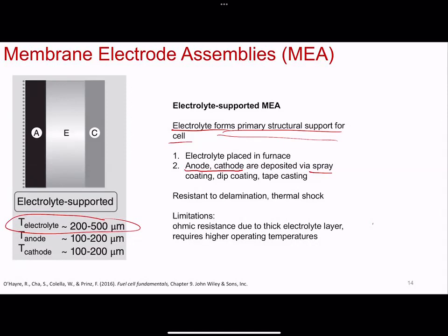Oh, wait, what was the first thing you said? Yes. So the question is, can you sputter? A potential problem, maybe it's not a problem, but something you have to consider with sputtering is that it is solventless, but you need a target. As in, you need whatever material you want to deposit. You hit your target, it sputters, and the material comes down. So you need this target.